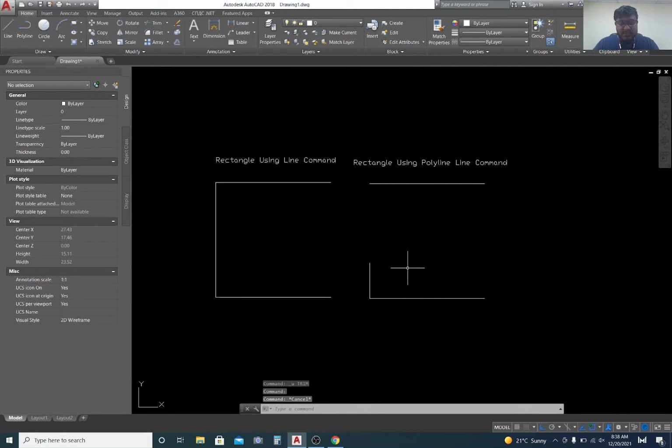Now we will use the extend command, where ex is short for extend. We can extend this line using the extend command. We have two commands which do the same thing. I will tell you why. When we are working on a big project and using the trim command, we don't have time to use the extend command to extend a line which was mistakenly deleted. For that, Autodesk has provided this in the trim command. When you press the shift button, the line is automatically extended to where you want.